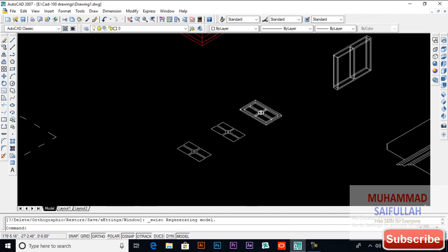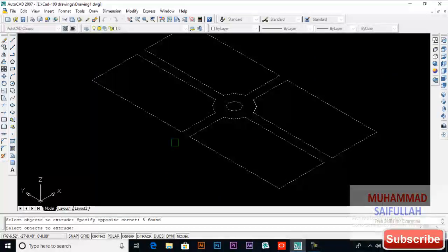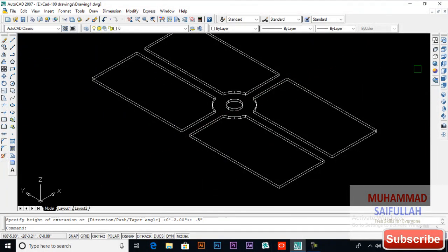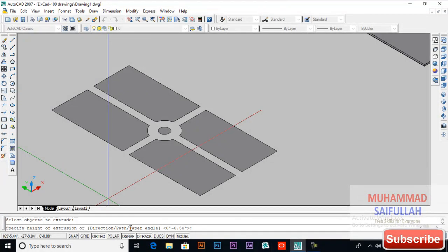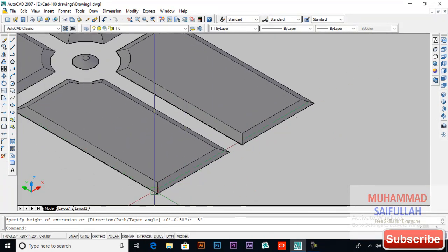So I will extrude it, select that all, and I will extrude it half inches. Now I will extrude it again, but I will have to give it a taper angle, T for taper angle, and you can give it a taper angle of 65 or 75. I will give it 65, and now you can give it a height of 0.5 inches. So that's how we created our design.